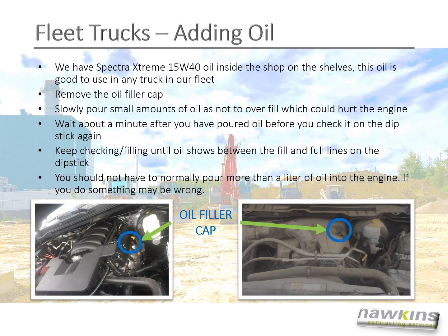Adding oil. We have Spectra Extreme 15W40 oil inside the shops on our shelves. This oil is good to use in any of our trucks in our fleet. Remove the oil filler cap. Slowly pour small amounts of oil as not to overfill, which could hurt the engine.